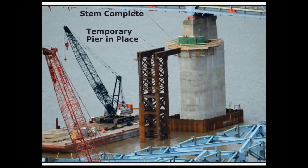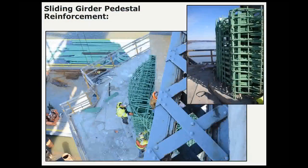The temporary pier is in place, and the rebar for the sliding girder pedestal is set and ready to be poured. You can see there's quite a bit of rebar in this pedestal because of the forces it experiences. Here's a close-up of that pedestal. I think there's just about as much rebar as there is concrete in that pedestal.